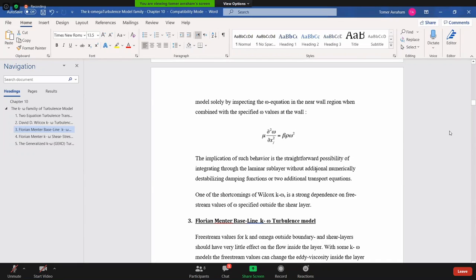In Reynolds-averaged Navier-Stokes, what you do is you decompose the flow into an average velocity and a perturbative velocity. And you actually model all the turbulence. All the turbulence is modeled. What you do in LES is you resolve the mesh ideally to the Kolmogorov scale, then you'll have a direct numerical simulation.